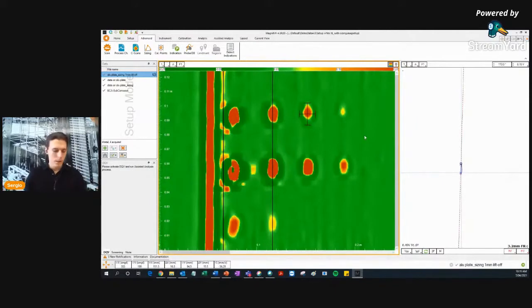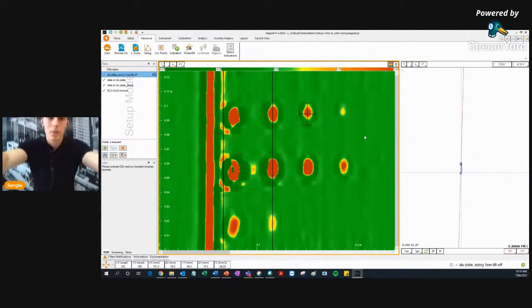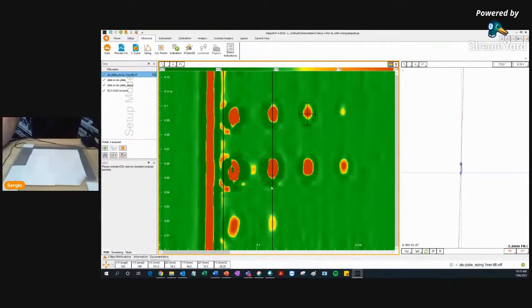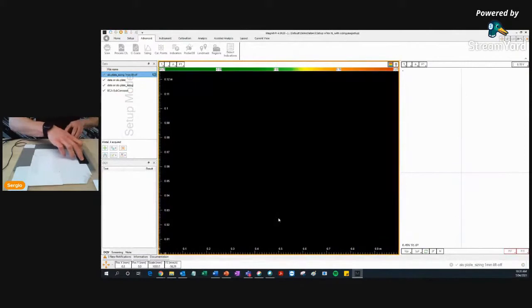So here I didn't have any lift up. So now we'll add a sheet of, let's say, 1 millimeter. And I'll perform the same scan, and just keep in mind how the scan looked, how well you see the indications, because now the indications should become a little smaller because we're a little bit further away from the surface. So balance, I scan, I try to move a little bit slower now. Don't have a black line.